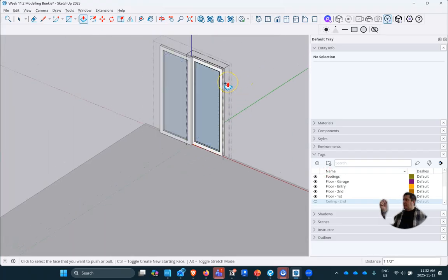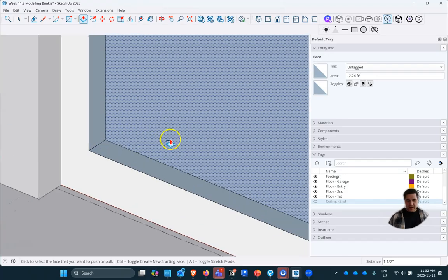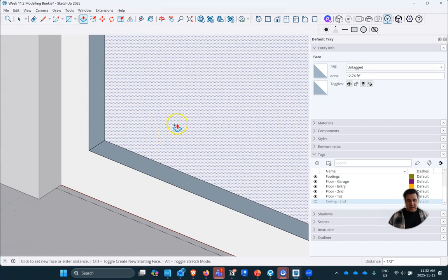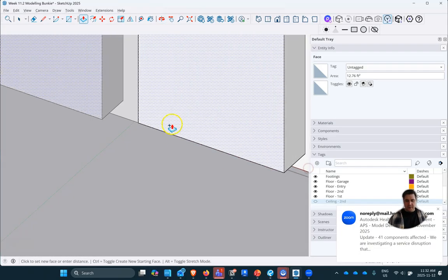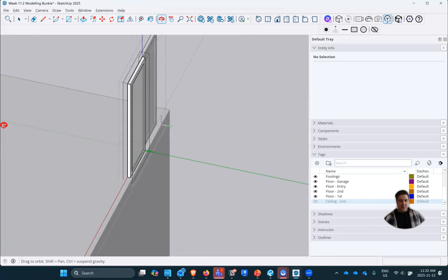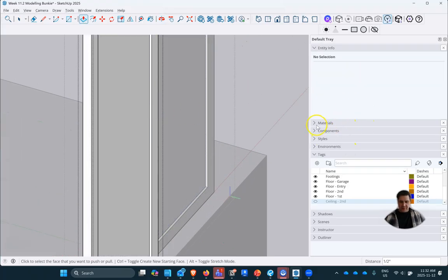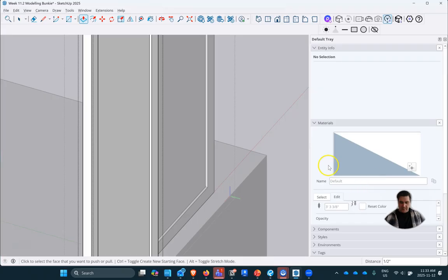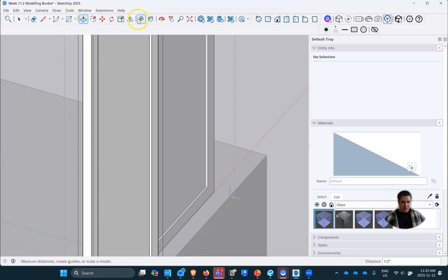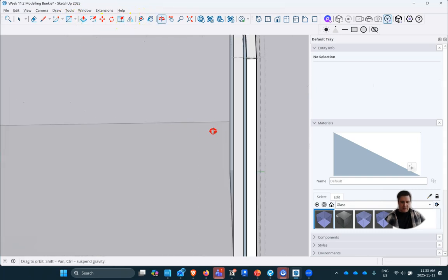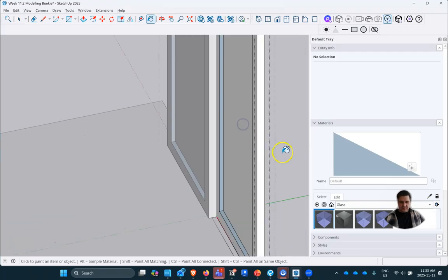And that glass is just like a paper thin piece of glass. Again, you can model that as 2 separate panes, but now that we extruded all the way through, we see the inside. And we can grab this piece again, and if we just look here, we can verify we're not moving the outside part, and we're not. So now we can just bring this in 1/2 inch. And so now we have 2 layers of our glass, and if we go into our materials, we can apply a material to them. So let's go to glass, and let's paint both the inside and outside layers of this.